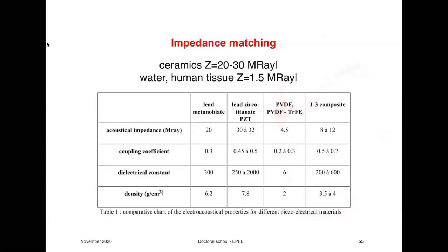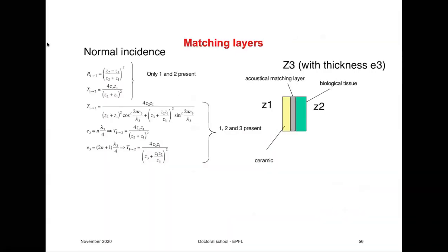Polymers, on the other hand, are the best to transfer acoustic energy from piezoelectric material into air. So you would use piezoelectric polymers to detect, for example, an explosion in the air, while for imaging, 1-3 composites are the best.